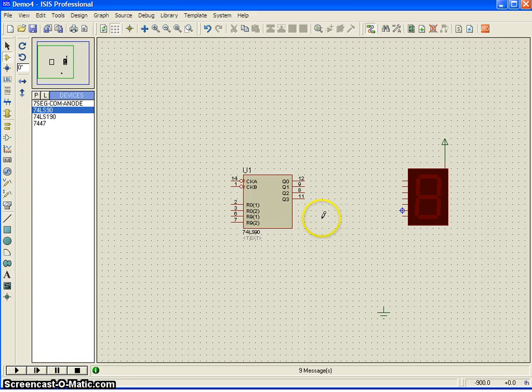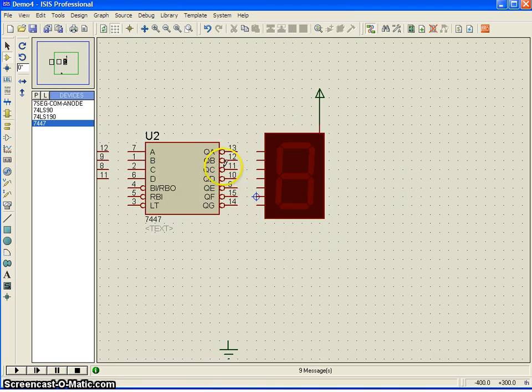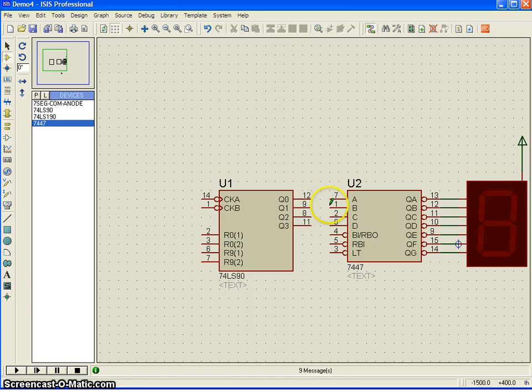Okay, and I have the display driver also here. So this is for A. I connect once, and look here, the wires must be of equal length. Once you connect and go to the next pin, just double click, and automatically the wire will be routed. But it must be the same length, then only this will work out. And I believe this will be LS47. Anyhow, we will check it out, and just connecting here.